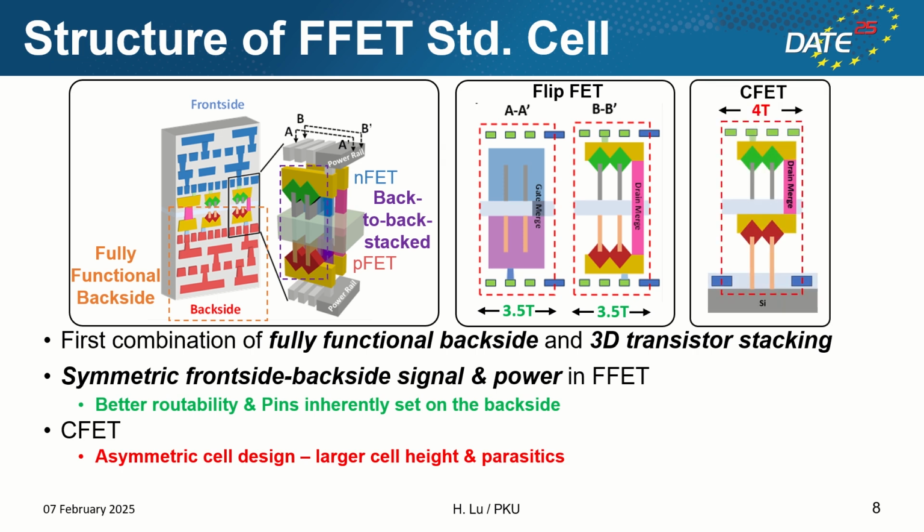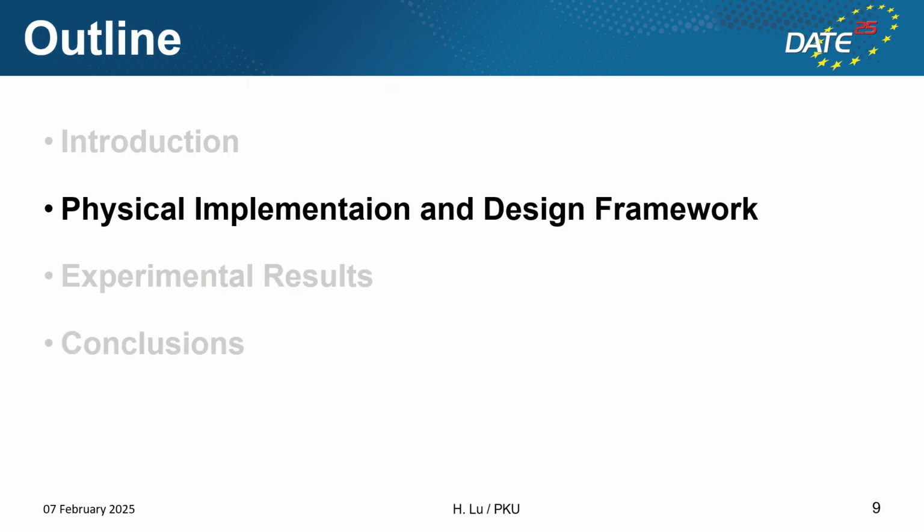However, the CFET uses asymmetric standard cell design. This will cause larger cell height and parasitics. Moreover, the CFET is not split gate friendly, and this leads to extra cell area penalty.